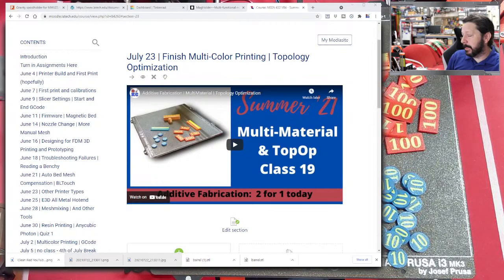What you do is you build the bracket in different ways depending on whether you're doing generative design or topology optimization. Today we're going to do the topology optimization. The software will eat away at it and iterate to find the minimum amount of mass that you need, and where you need it, in order to support whatever kind of load you're trying to support.